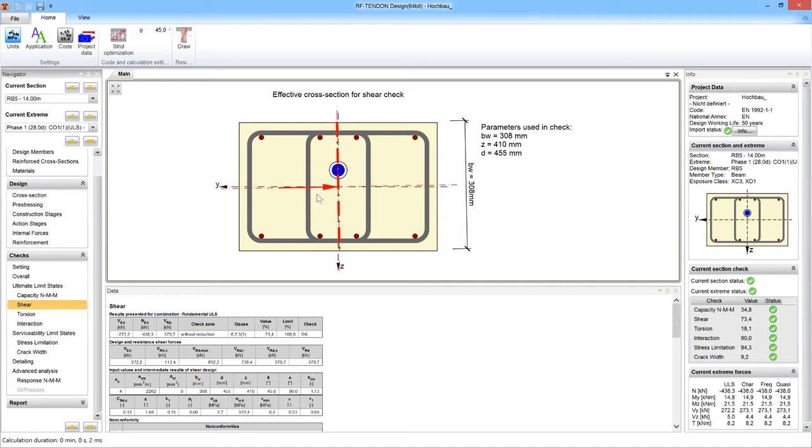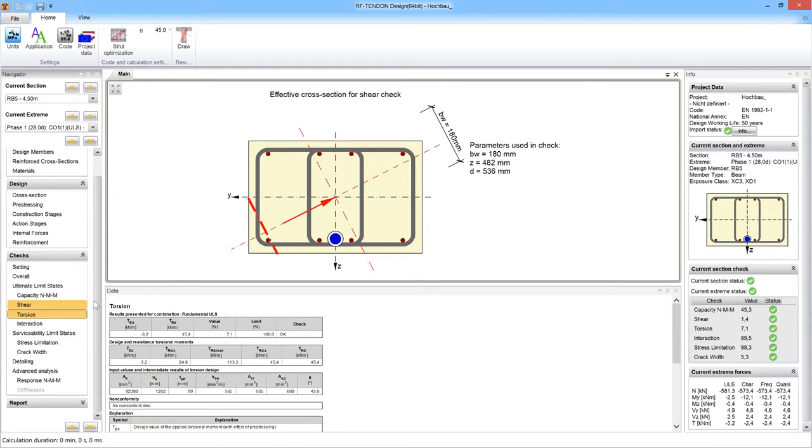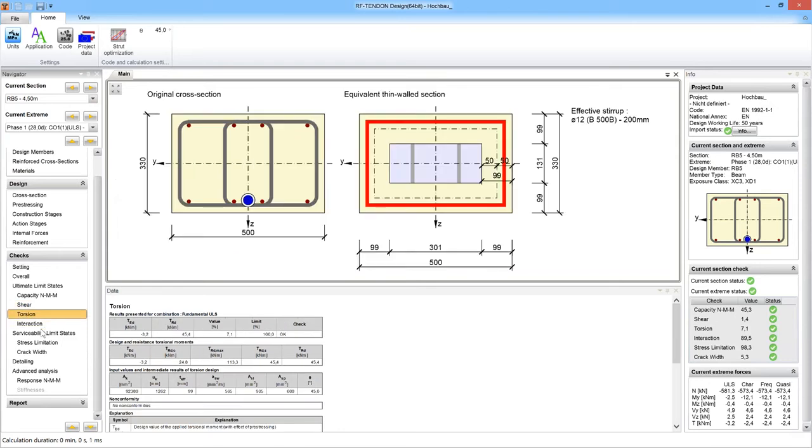If we apply a high normal force of pre-stressing, then of course just behind the anchor we should not use the sectional analysis. It is the anchorage zone, but I don't think I made it immediately after the anchor, and still RFEM integrates quite significant forces, but we can design them with no problem. So let's go back to the midspan. Maybe I should have shown this torsion above the support, but it doesn't matter.